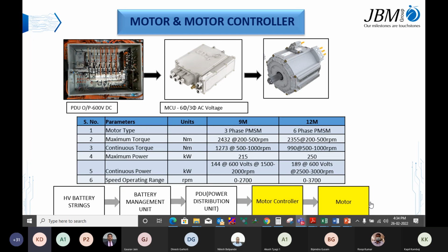Akash, Krishna this side. I have one doubt. Why are we using the PMSM basically? In place of PMSM, we can use the induction motor with the help of VFD, because the magnet in a PMSM has a tendency to lose its magnetism over a period of time, and we are using this motor in a vehicle for 12 years, 15 years. Right, sir, so it will deteriorate the life. Certainly.